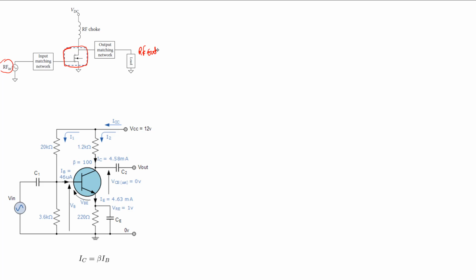So apart from the transistor, there is going to be an input matching network and an output matching network that is going to achieve the so-called conjugate match for the input and the output load, to transform the load impedance such that it becomes the complex conjugate of the looking-in impedance of the transistor, and similarly the source impedance is going to be transformed to its conjugate in such a manner that the looking-in impedance is going to be the conjugate of the input impedance of the amplifier.